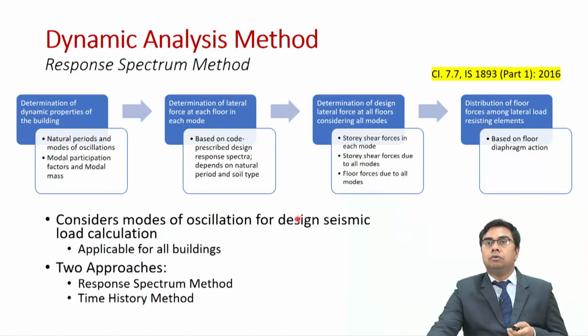Now, the good thing about the dynamic analysis method as compared to the equivalent static method is that different modes of oscillations are also considered in this case. It is not only based on the fundamental natural period, but it is based on various modes of oscillation which pertain to different natural periods of the building. This makes it applicable to all the buildings.